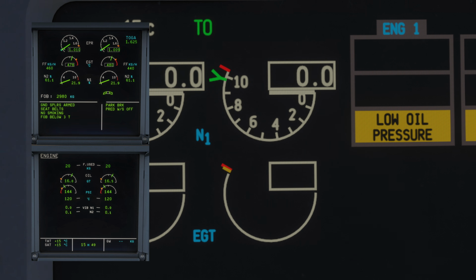can combine those two. And that's how they created the thrust indication that you have, for example, on the A380, A350 and the Boeing 787, if those are featuring the Rolls-Royce Trent XWB engines. What they do is take the example of N1 with an easy figure between 0 and 100%, and mathematically compute the EPR figure into that thrust percentage, which you then show to the pilot. That makes it very easy to control your engines and gives you a very precise output.